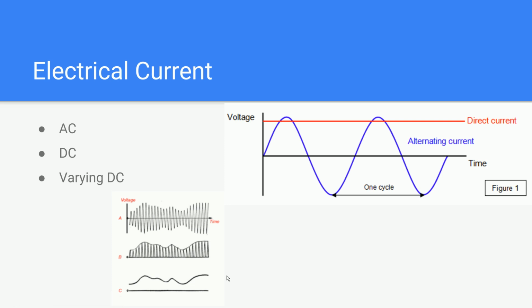One example of all three of these is, say, an AM radio broadcast. The carrier wave, or the wave that carries the audio signal, is, say, for AM 550, 550 kilohertz, or 550,000 times a second it goes back and forth. When it does this, they're modulating the voltage corresponding to the waveform of somebody talking, or music, or whatever you want.